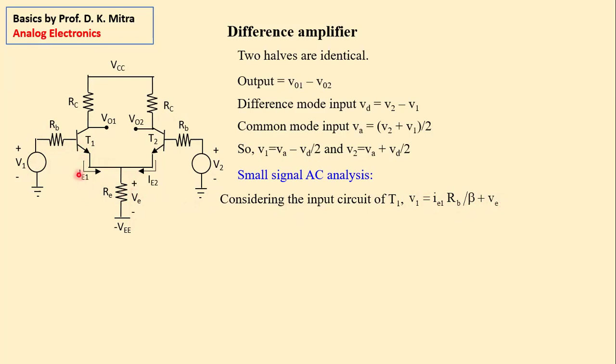One is there is a base emitter voltage, VBE. Also, there is a base emitter resistor, HIE. But these base emitter voltage and base emitter resistance values are very, very small. And also, since the circuit is symmetric from the left-hand side and right-hand side, ultimately they will get cancelled out. So to make it very simple for you, I have left them out. So this is V1. Now apply Kirchhoff's voltage law to transistor T2.